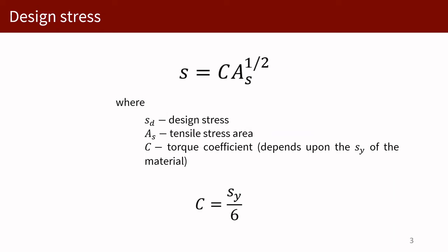So the consensus among engineers and their derivations later settled into using a circular approximation. Thus, this is the equation. Instead of the root area, it is generalized, so the stress area can be a root area or the mean area of a threaded component.